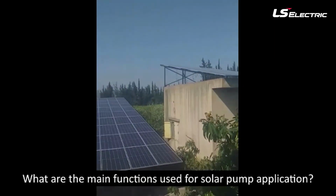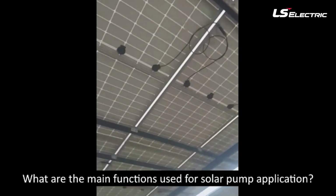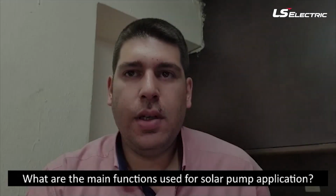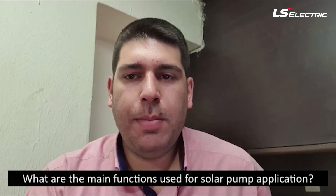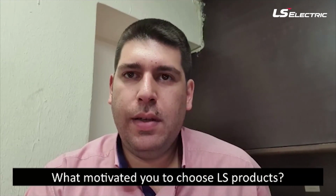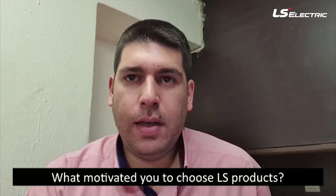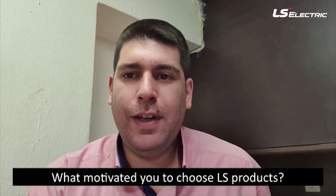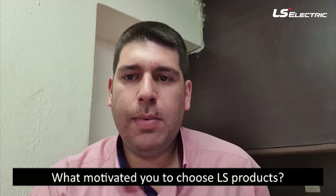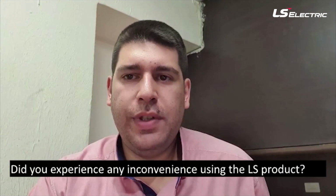H100 has multiple protection functions such as dry run that helps protect the pump and are very well implemented in software. It also has extra versatile functions such as solar PID, which allows pressure and flow control during MPPT applications. Recently, many more customers want to pump 24 hours a day by connecting to the grid or generator. We are developing a function with LS and are planning to test as soon as it is ready. I am very excited. I also heard that LS is developing functions that can control multiple pumps without the PLC in solar pumping system. I'm looking forward to using it.